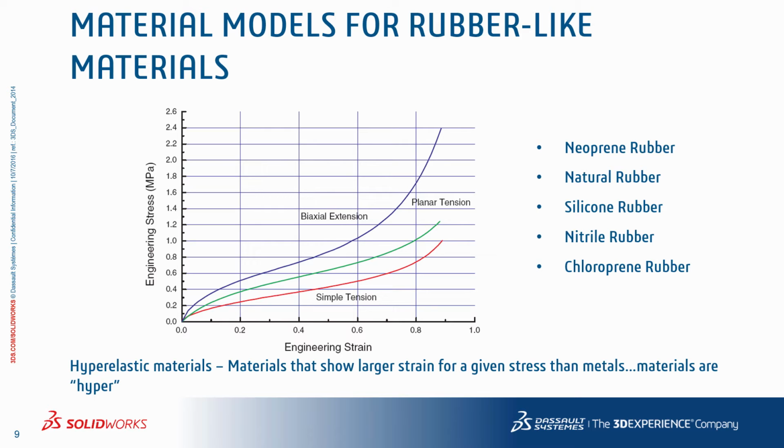Now, due to the complex behavior, the elastic constants or material constants are derived from the elastic strain energy density. These material constants are what is needed in SOLIDWORKS Simulation. The good news is that if you're simulating these materials, then it is highly recommended to get the stress strain data from the material vendor and use it in SOLIDWORKS Simulation. That way the program will calculate the material constants and use them for the solve, rather than you trying to figure out how to calculate the material constants.